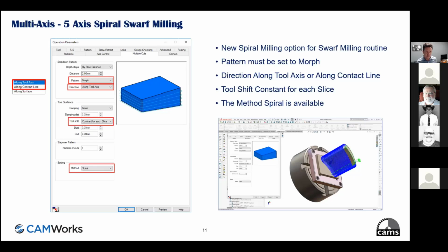I think that's awesome, because it's going to helical down around that part and continuously drop as it's going down, so you don't have any witness marks where the tool may lead on or off, or feed straight down along the surface. So it'll help get a nice, cleaner surface finish. Yep, and saves time too, right?